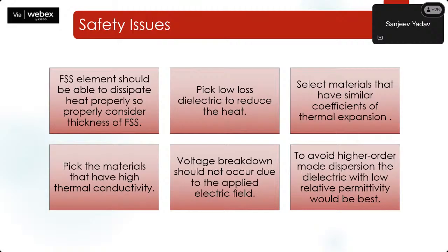There are some safety issues in the case of FSS. The FSS element should be able to dissipate heat properly, so consider the thickness of the FSS properly. Pick a low loss dielectric to reduce the heat, because some signals are transmitted, some are absorbed, and some are reflected. So the energy is not destroyed; either in the form of heat or in the form of reflection, it is going somewhere. So we need to choose a dielectric that can reduce the heat.